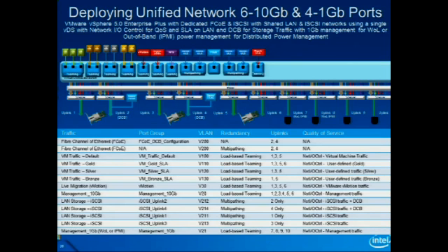The adapters still are going to be challenged because the PCI spec for standby power is like less than a watt or something like that, 300 millivolts or something, and unless you can get down to 100 megs and your PHY can drop down enough of your filters to get down to that power requirement, it's challenging.